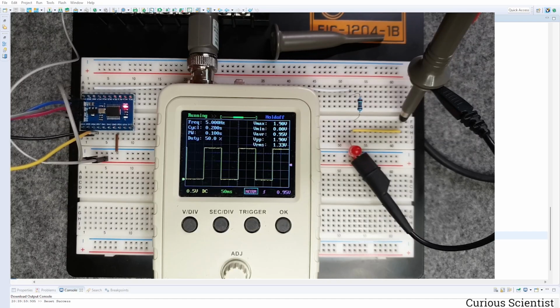So first of all, we created a lower frequency by dividing the system clock frequency 48 megahertz by 48,000. So that is 1 kilohertz. And then we know that from 1 kilohertz, that is 1 millisecond of period. And then we want to count up to 200 of these periods, so 200 milliseconds.